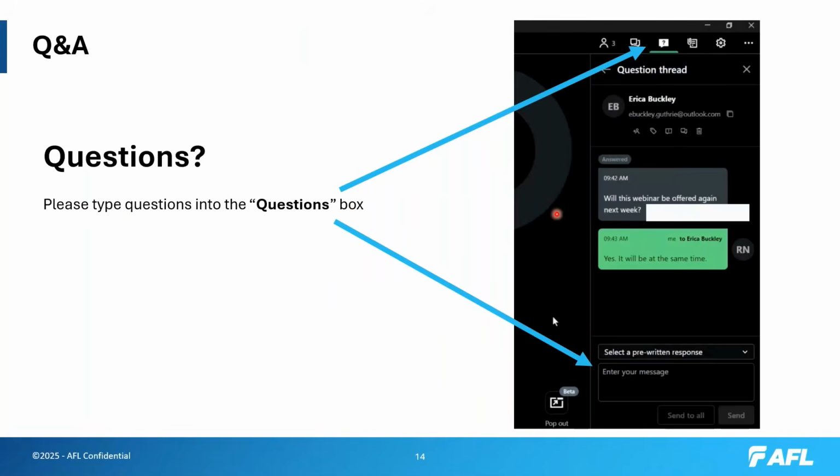So do we have a recipe for that? The recipe is controlled by the machine's quality control. When you do an arc calibration, this will automatically tune that splicer for doing 12 fibers, 1 fiber, 16 fiber. So you just have to do periodic arc calibrations or diagnostic tests within the machine's main menu. Very simple operation, takes about 5 minutes, and highly recommended you do that on a daily basis.